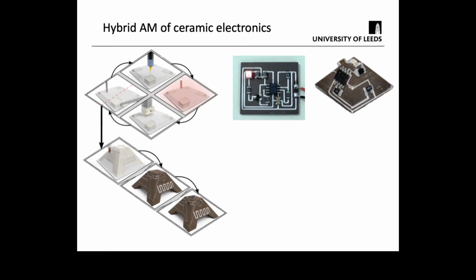You probably noticed on the slide where we're putting the conductor down that we're using a 3-axis Cartesian system. That certainly has some limitations, and maybe there are some advantages of moving to additional degrees of freedom, like a 5-axis system, or being able to control the motion of the substrate and kinematically linking that to the deposition head will give additional complexity with the manufacturing.